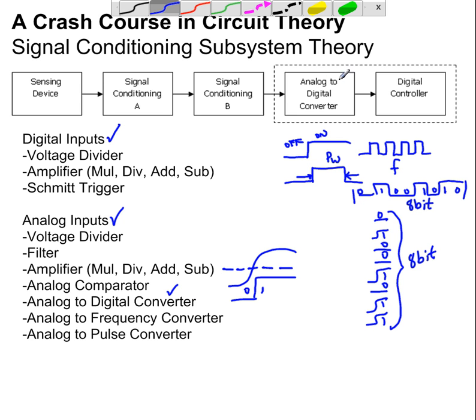Most microcontrollers today have analog to digital converters built inside. These come in various sizes. It could be scaled to 4 bits, 8 bits, 12 bits, and even 16 bits. It depends on the range, or how many points along this analog curve that you need to read. 4 bits allows you 16 different points along this curve. 8 bits allows you 256 points.